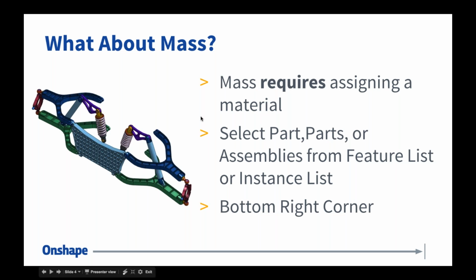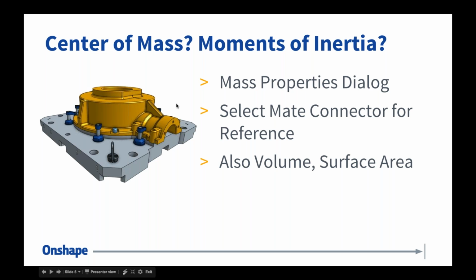Now, one last slide for you before I get into the actual measurements and such. There are other questions associated with mass, things like center of gravity or center of mass, or moments of inertia. And all of these things, including volume and surface area, are also inside of that mass properties dialog. So whether you're looking for the weight, the volume, the surface area, the moments of inertia, the center of gravity, it's all within that one dialog.